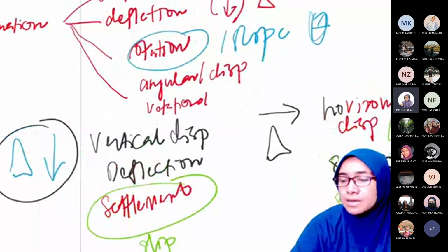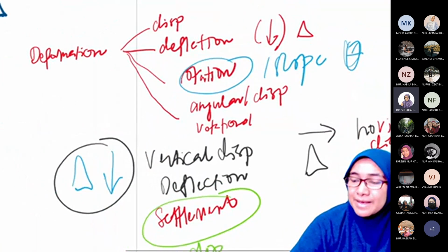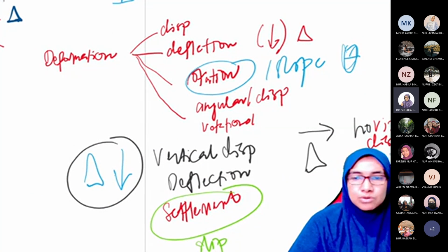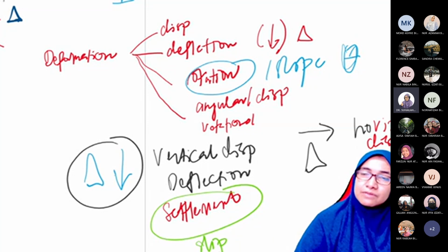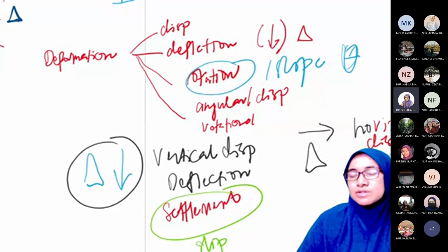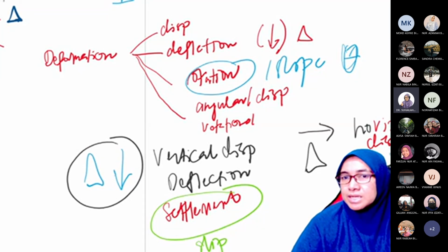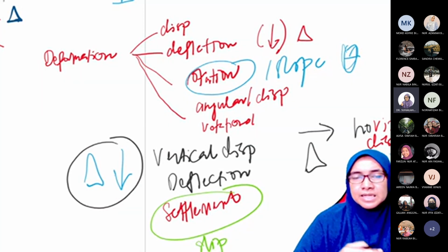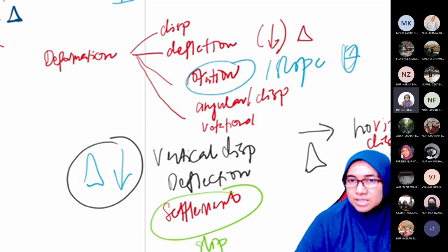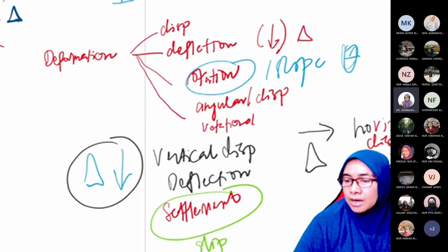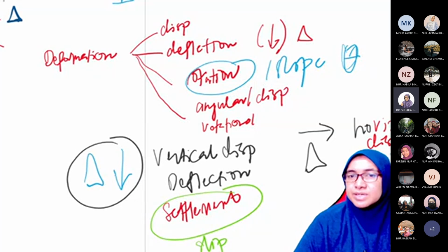So these are all names for displacement. There are many names representing the same behavior. It represents deformation, change of shape. So what we commonly use is delta and rotation. Deflection and rotation. What does deflection refer to? What does rotation refer to? Rotation is also called slope, representing rotational displacement. Its symbol is theta. The symbol for rotational displacement is theta, and for deflection we use delta.